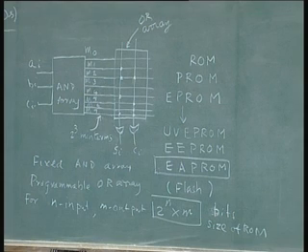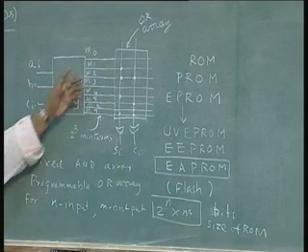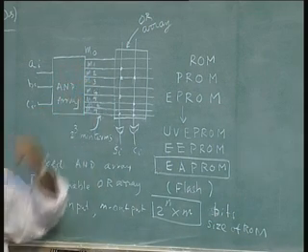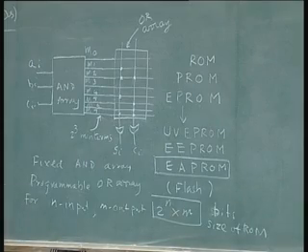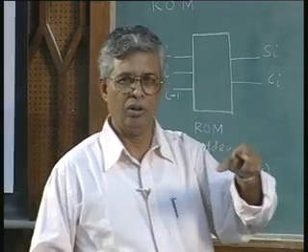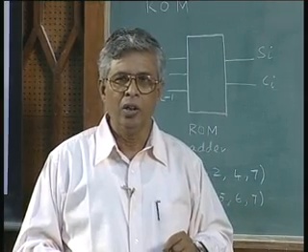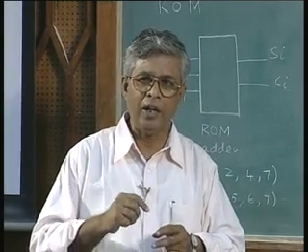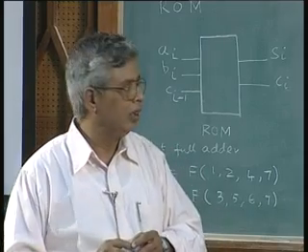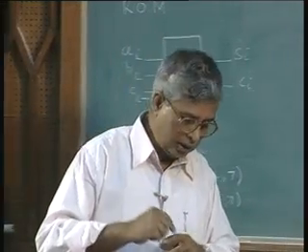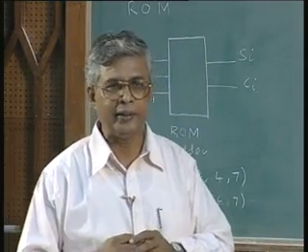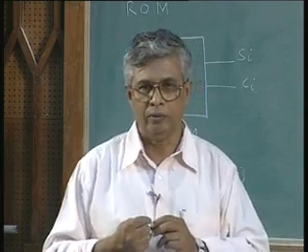That means most of the min terms that are generated will not be used in the output. This is a waste of hardware or silicon real estate, as they call it. So, for these two reasons, that is underutilization of the size and an exponential growth in the size for very large applications, we want to have another alternative.